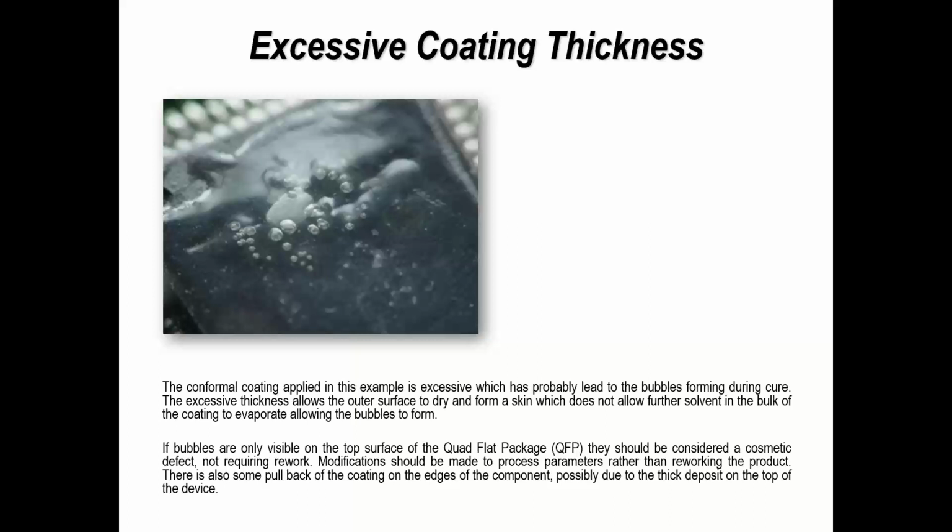So, two things. One, the thickness of coating that's been applied to this particular component is excessive. There's no question. I can tell from here, and I took the photograph, how thick it is. But the point is that the more you put down, the more time you've got to allow for any bubbles, entrapped gaseous materials to escape before the surface tends to dry out, tends to cure, because then the bubbles won't come out if you haven't got time for them to escape. But if you put more and more on, you get more and more of a problem.